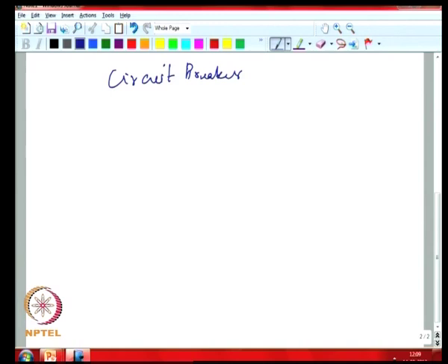You have electromagnetic circuit breakers, and many larger breakers available today have electronic trip units which operate to decide whether the breaker should open or stay closed. So, you could have different control packages to operate the breaker. The actual breaker is a device which would make or break the current. Whether it should open or close is decided by your trip unit.